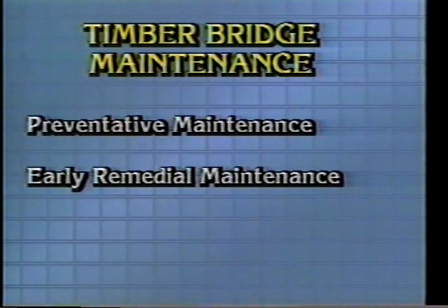In this situation, decay is present in the wood, but if corrective measures such as in-place treatment and perhaps replacement of some of the minor members such as curbs and railing members are done, the structure will be able to remain in service for many years to come.